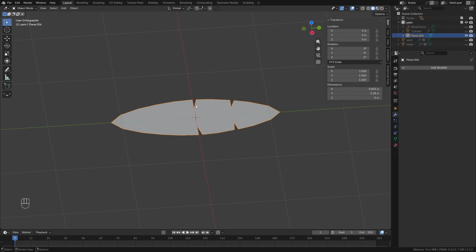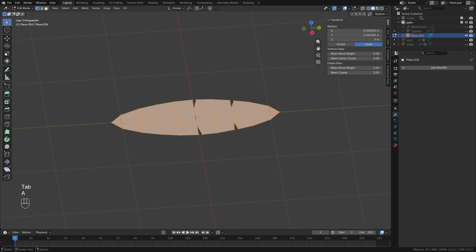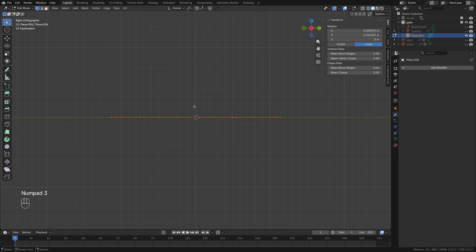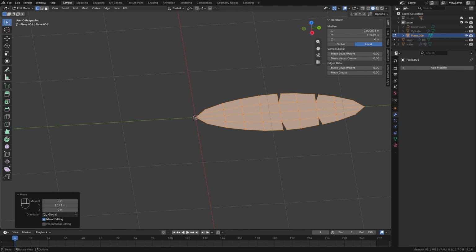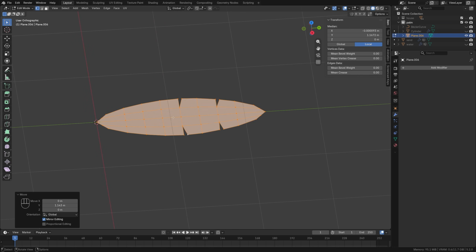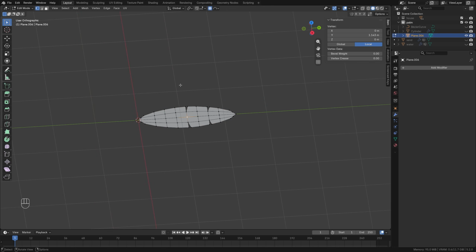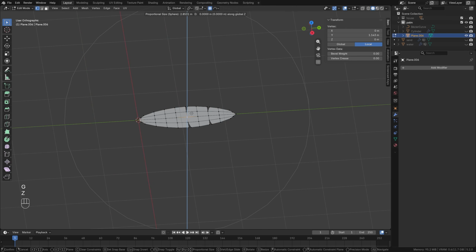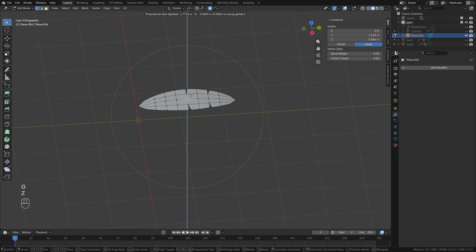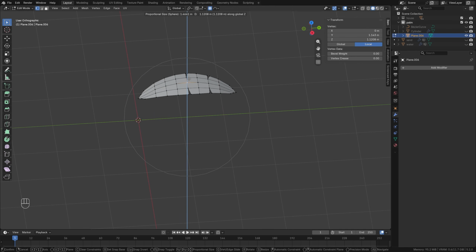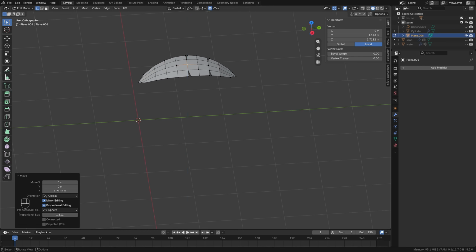And here now again in edit mode, we select everything. On side view, we shift everything along the Y-axis. We make it so that the extreme vertex is located in the center of our object. And then we select the central vertex, turn on proportional editing, press G+Z and raise all this. Adjust the radius and thereby curve the shape of our leaf. Well, roughly in the following way you can adjust this. Let's take an even bigger radius and here, possibly, curve it in this way.